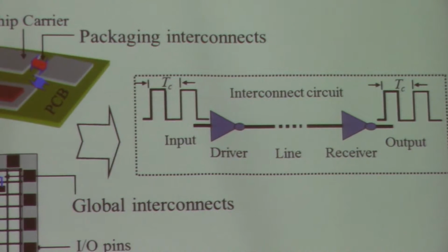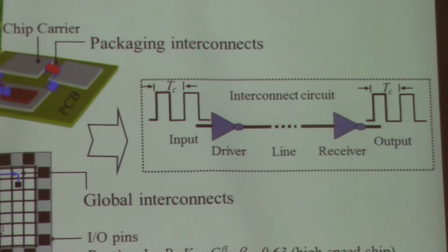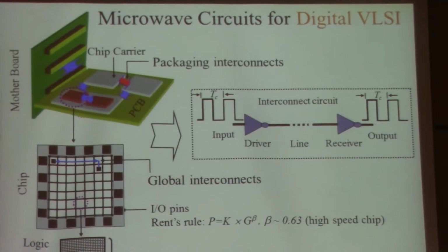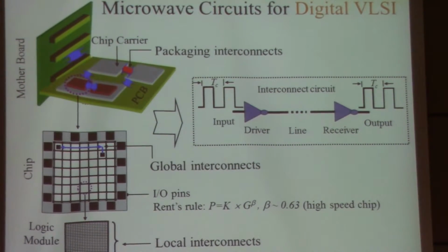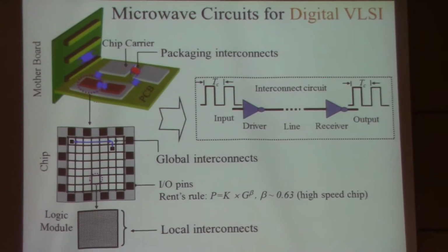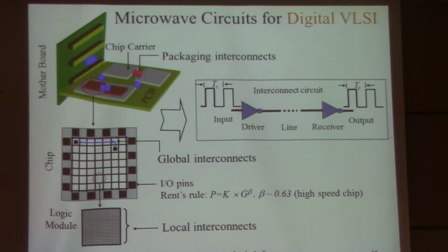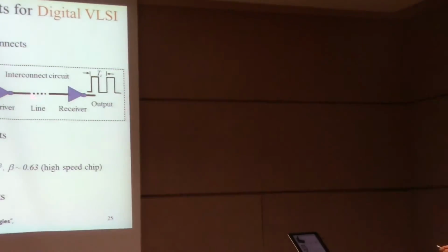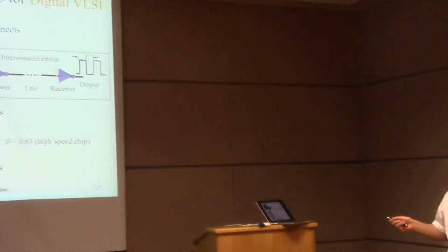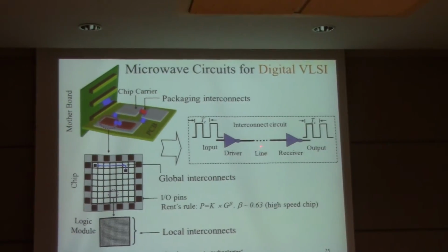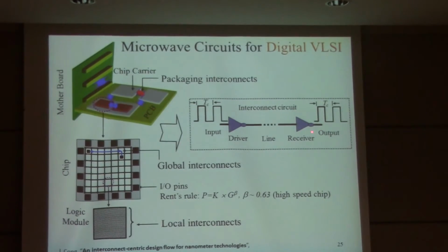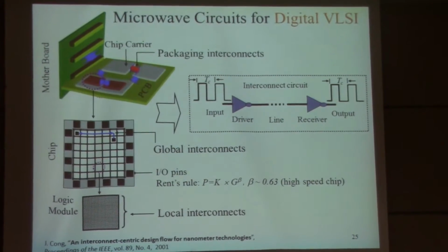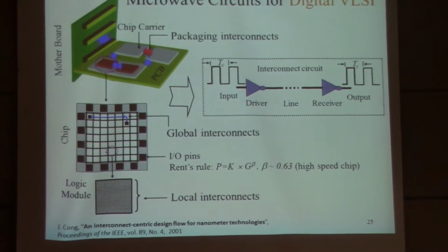And this dispersion actually is very important for digital circuit designers, not only analog designers, not only RF, because if you break open your computer chip, right? If you look hard, your computer chip can be summarized by this very simple circuit, where you have a driver, you have a receiver, and you have an interconnect, right? This can be the inverter, that's it. Okay, break open your computer chip, that's what you get.